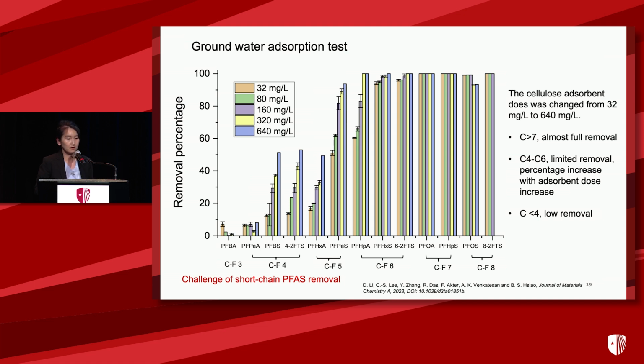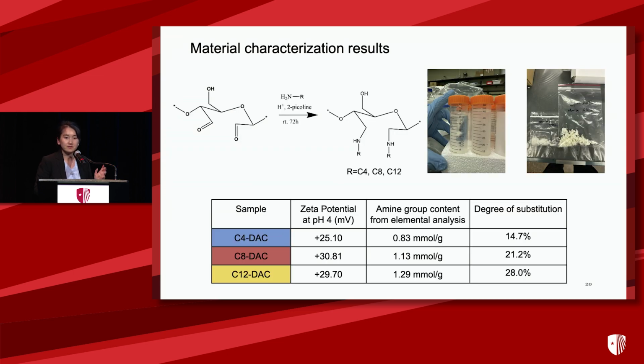We have almost above 90% removal of the long-chain PFAS. However, we still have challenges for short-chain PFAS removal, PFBA and PFBEA, even at higher doses of this adsorbent.